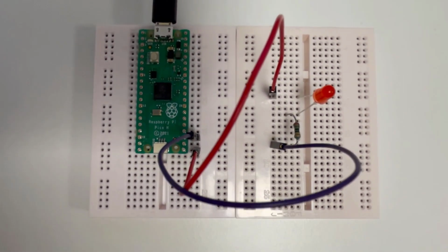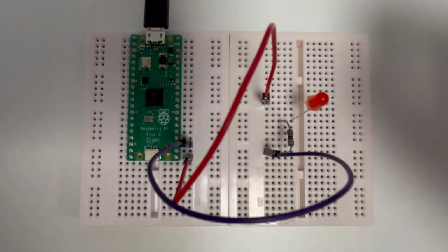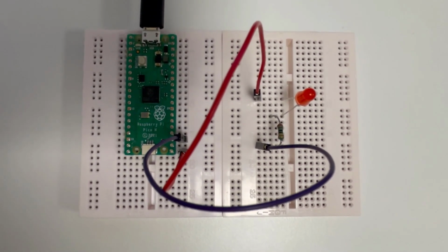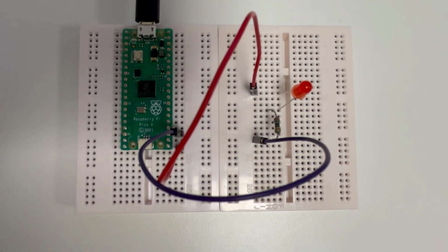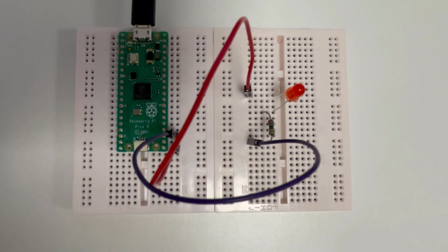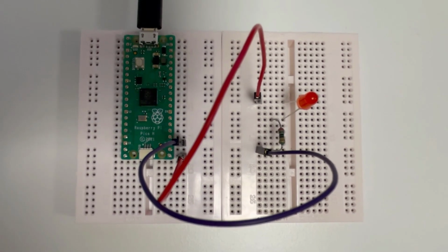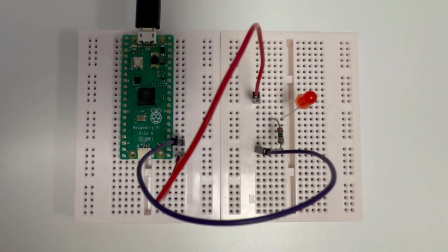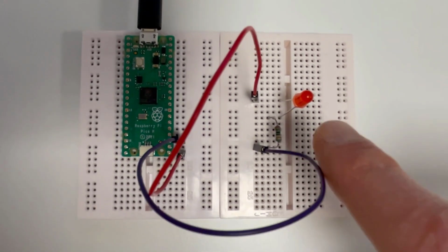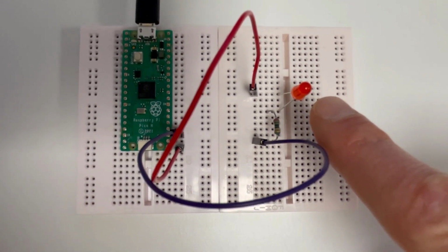Here we see a demonstration of this pulse width modulation. Now when I turn on the program, you will see that the LED will increase step by step. It will take a couple of seconds going from 0 to this 65,535 level. Now I will click on the run button and observe the LED, and you see the level of the LED was increasing step by step. Let's run it once more, and you see the LED was increasing, and finally I just shut it down at the end of the program.